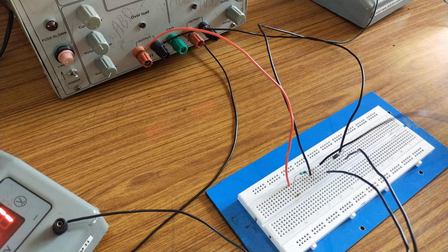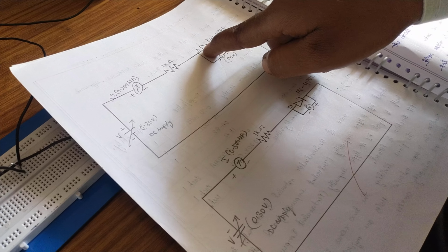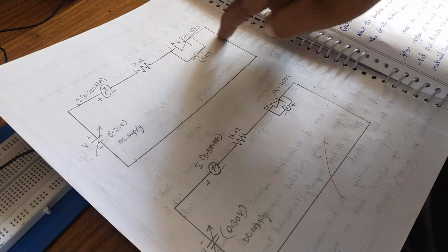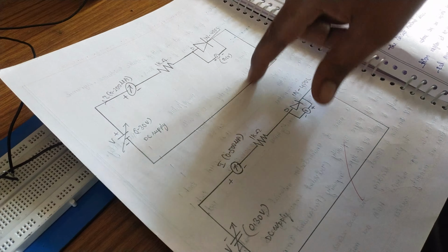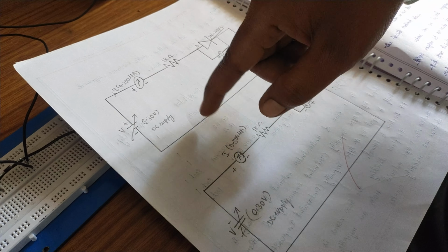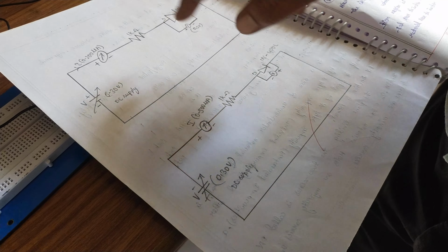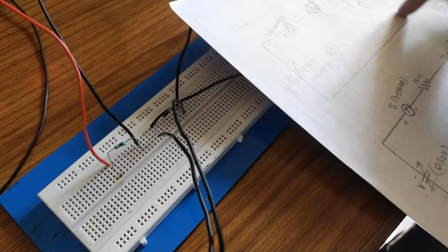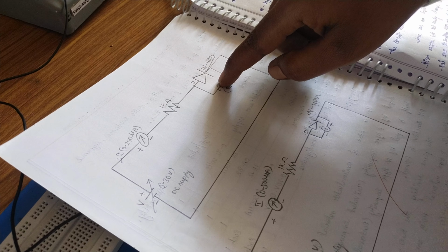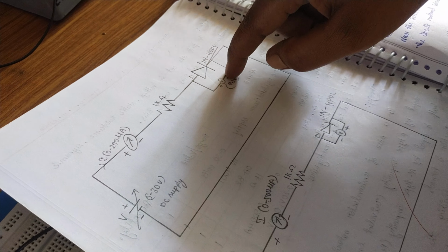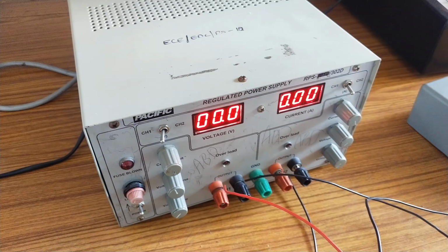According to this forward bias and reverse bias circuit, when the positive terminal is connected to the diode anode and the negative terminal is connected to the diode cathode, it is called forward bias. Quite the opposite, when the negative terminal is connected to the diode anode, it is reverse bias. Now we are going to conduct the experiment on forward bias, to see how the diode works. This voltmeter shows the voltage across the diode. The supply voltage is measured by the meter.